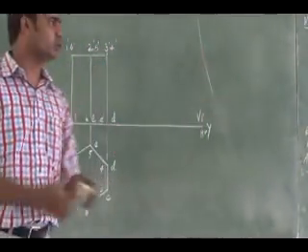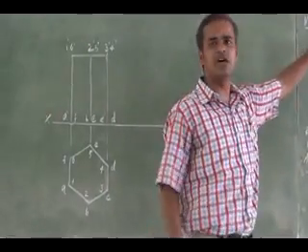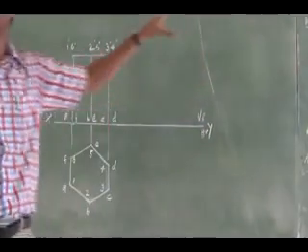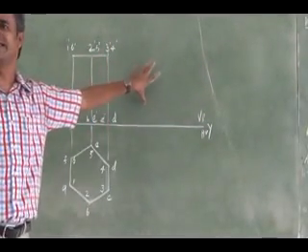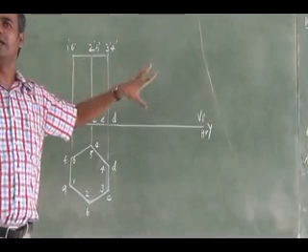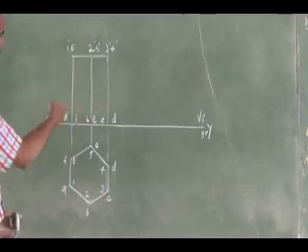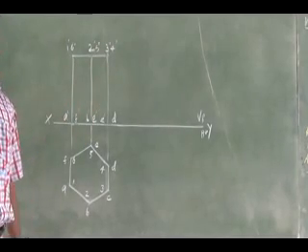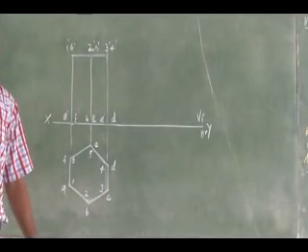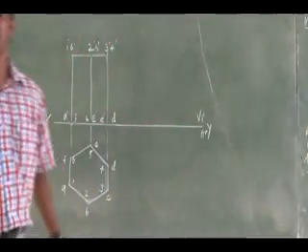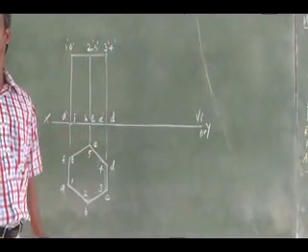Same problem. So I told you this is the one change of position method that we have seen. Just the front view, you have changed this position to 30 degree incline to the horizontal plane. You have drawn the front view and top view. Right. Here, this is another method I told. It is the change of reference line method or auxiliary projection method.